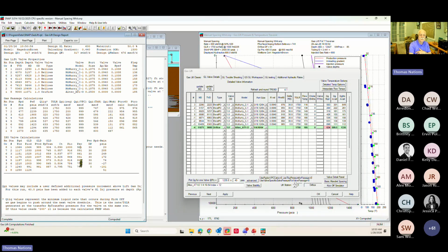So those are the surface closing pressures that when you go out to the well, if the well's operating at 600 barrels a day, 600 MCF injection gas, injecting at the bottom, then these are the gas injection pressures you should see at the surface. The gas injection pressure you see at the surface is related to that surface closing pressure and ends up being very close to that, just slightly above that.